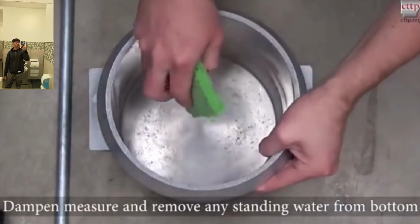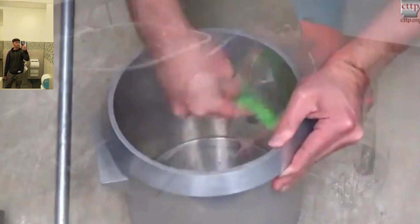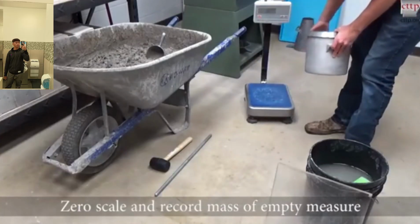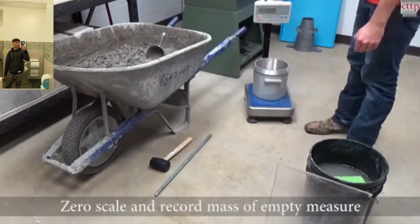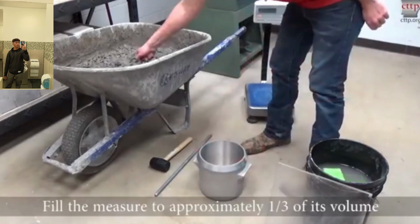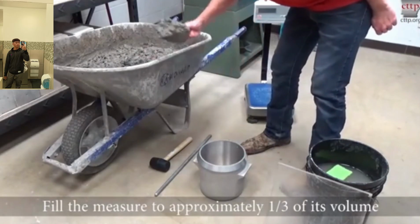First of all, dampen the measure and remove any standing water from the bottom. Zero the scale and record the mass of the empty measure. Fill the measure to approximately 1/3 of its volume.